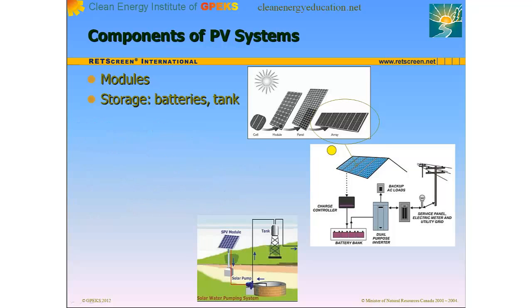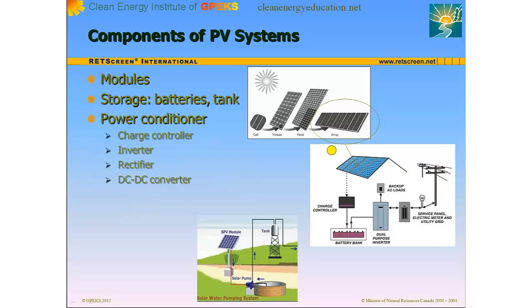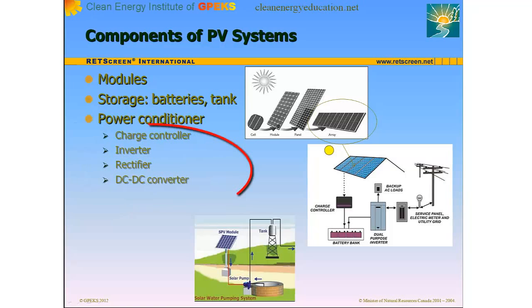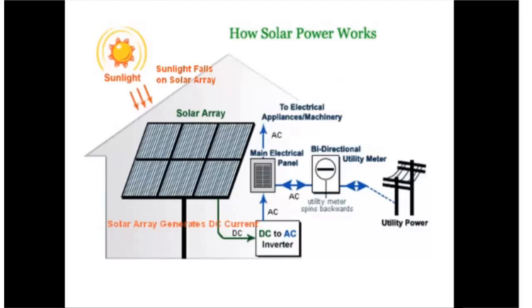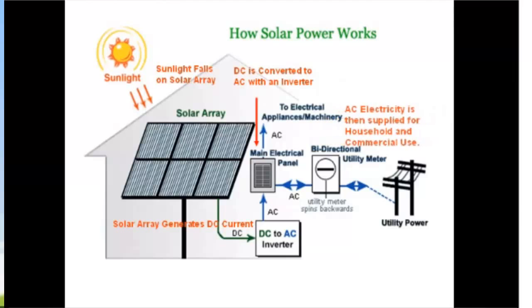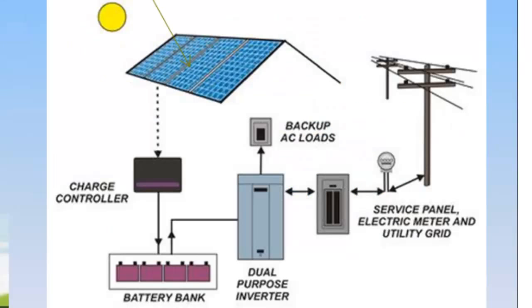Photovoltaic systems may also include electronic power conditioners. These manipulate the output of the array such that it matches the current and voltage requirements of the load. Inverters are common power conditioning devices that convert direct current into alternating current. With an inverter, the PV system can operate common appliances designed for grid power, such as standard washing machines and televisions, or feed its power onto the grid itself.